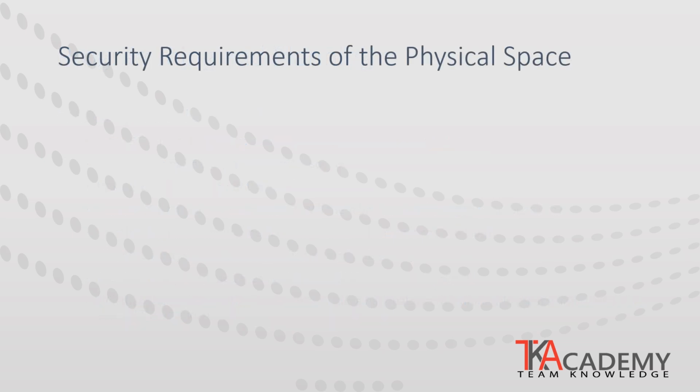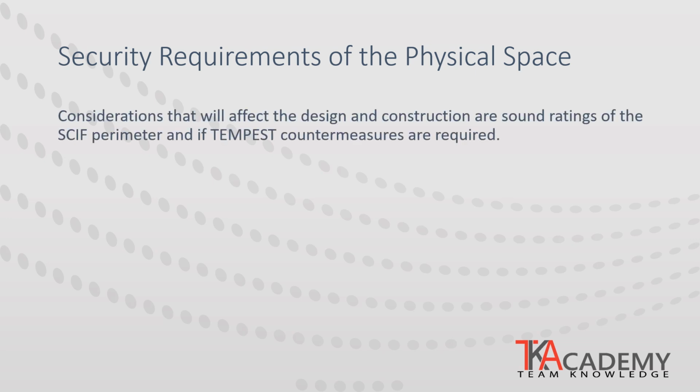The existing security requirements of the physical space must be considered in SCIF planning. Considerations that will affect design and construction are the sound ratings of the perimeter and if TEMPEST countermeasures are required. Will there be areas that are designated as non-discussion zones, such as stairwells, vestibules, storage areas, and restrooms?